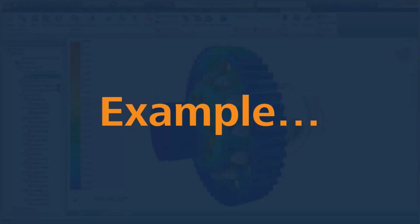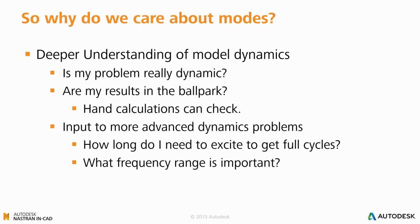Let's go back into our presentation and just quickly finish up. So why do we care about modes? Well, it's going to help us get a deeper understanding associated with the model's dynamics. So it's going to firstly tell us, is my problem really dynamic? And it's also going to give us an idea as to whether the results that I'm getting are inside the ballpark. We can validate the results that we're getting using books such as Formulas for Natural Frequency and Mode Shape by Robert Blevins.